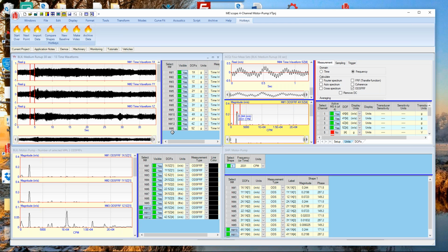Well, no, there's 12 response channels and then the reference down here. So 13 channels of data. And you can see the measurement numbers, which we use for animation and so forth. Number 6 was actually 0.2 in the Z direction. So if we go back to the model, we're just using that data to simulate the reference accelerometer, and we're calling that 5Z. Here's all the data in G's.